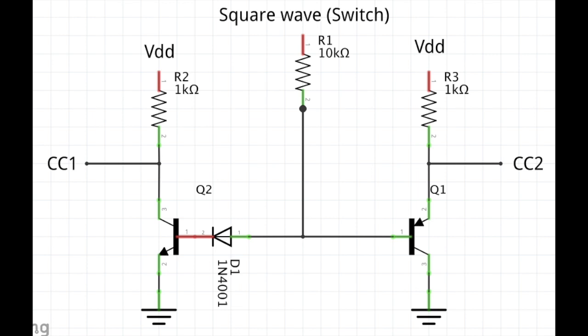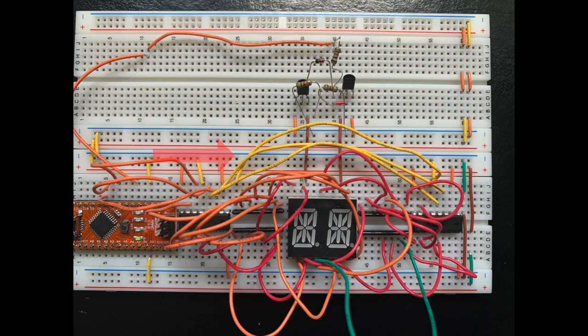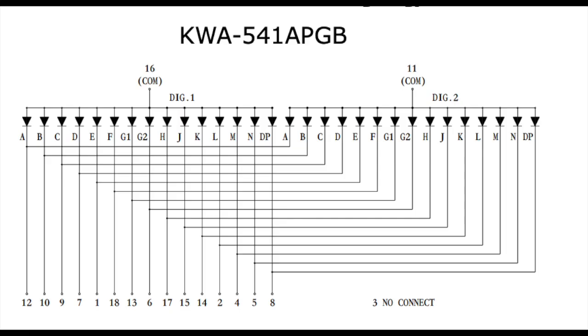To build the first portion of the circuit, a square wave signal must be built. A circuit diagram is on screen. From there, the IC chips must be daisy-chained together. Then the distinguished outputs from the ICs must be wired through the resistor networks and into their designated 14-segment display pins.